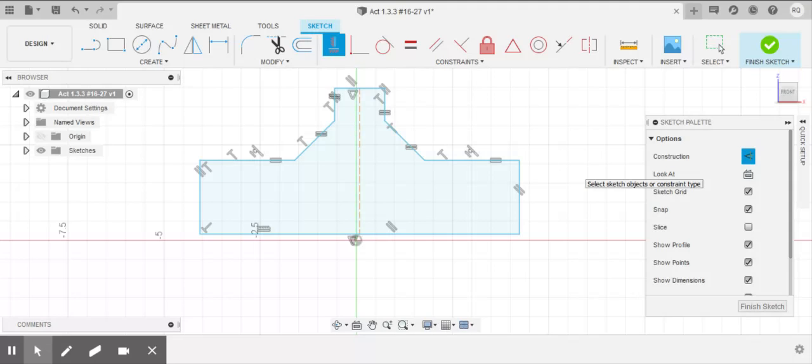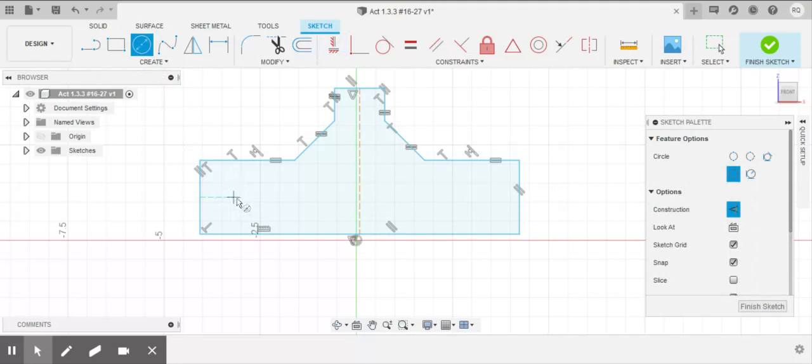24 says to draw a circle on our sketch kind of right here. So I'm going to click on circle. And I'm going to draw a sketch right here. It tries to pin to the midpoint. We don't want to do that. We want to kind of be here. All right. So it places a center point. And there we go. There's our circle.